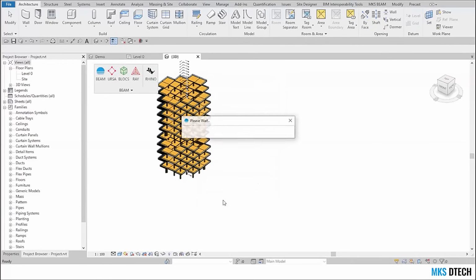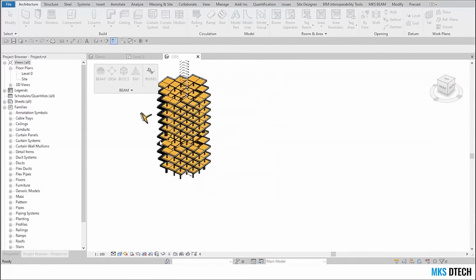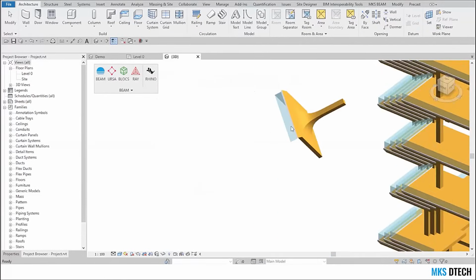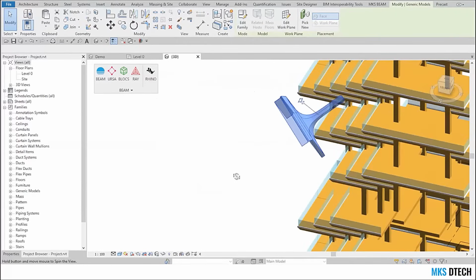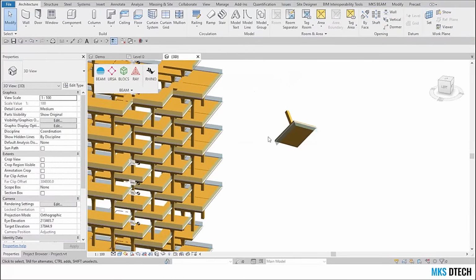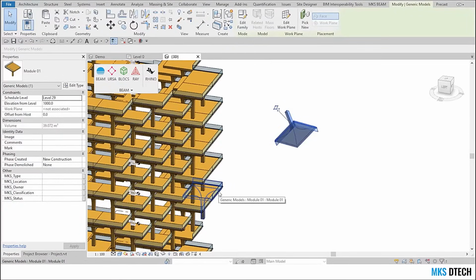When I click it, it's much faster because I don't have to import. I'm just placing this instance, and I have this block placed in this weird position. It should be quite difficult to achieve, and it is also assigned to the level that makes more sense. All right. So I can place imported families, but I can also place any family. I'm going to see that now.